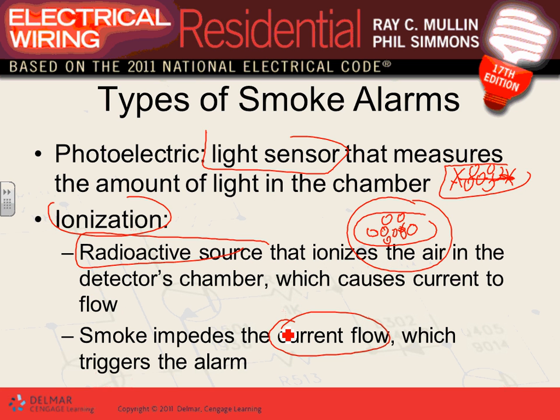You're going to see a lot of people coming here when we talk about smoke detection for commercial building fire alarm systems, talking about the same technologies. Photoelectric uses a light sensor that senses a light beam, or radioactive, which creates a current from the radioactive material. If the smoke gets into it, it interrupts the flow of that current because the smoke prevents the current from going through.